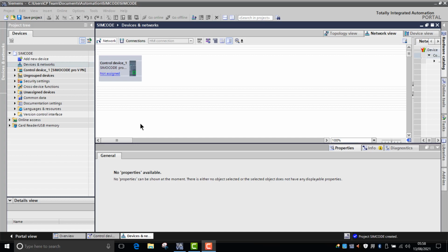In this example, we're going to jump into the ground fault and explain how that works and why you'd want to use it. Ground fault monitoring serves as an early warning system. Basically it provides operators with the information they need in order to plan appropriate maintenance measures. Measuring the resistance of a system's insulation to ground enables detection of both symmetrical and asymmetrical ground faults.